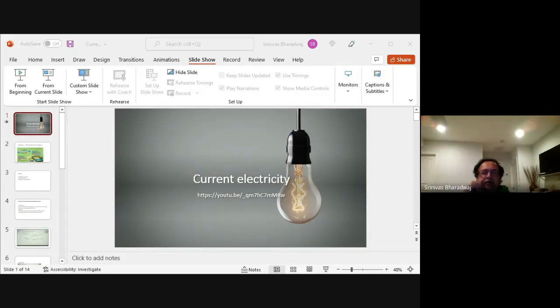So you add up all the power. 15 times 40, 600. 5 times 100, 500, so 1100. 5 times 80, 400, so 1500. 1500 plus 1000, 2500. So 2500 is the power. 2500 equals V times I. So what is the I? Right? So 2500 by 220.